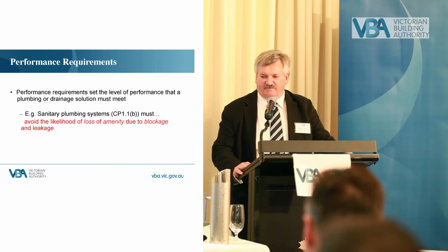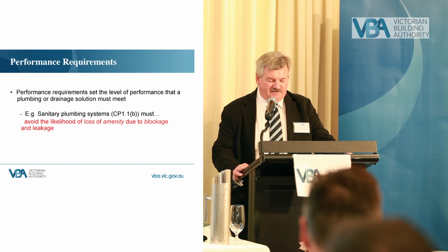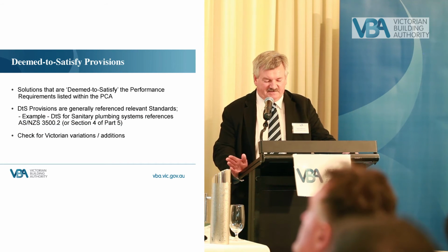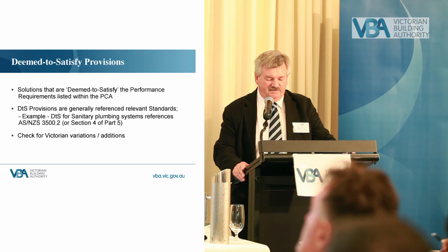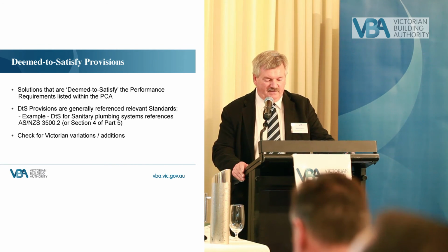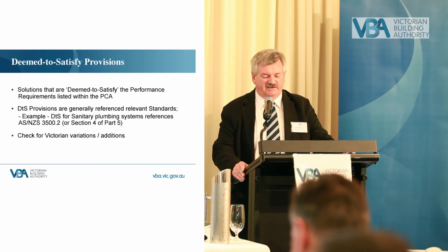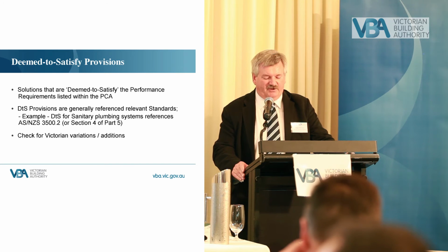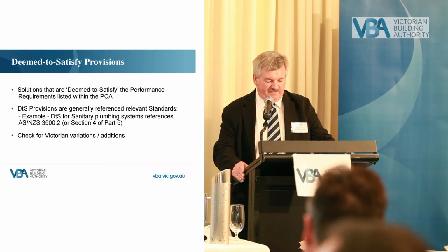The deemed to satisfy provisions. So how do you comply with the sanitary plumbing system performance requirements? As you saw before, you use a deemed to satisfy solution or an alternative solution. Deemed to satisfy provisions, or DTS, are the most common. The DTS solutions in the PCA predominantly refer to Australian standards and other technical documents.